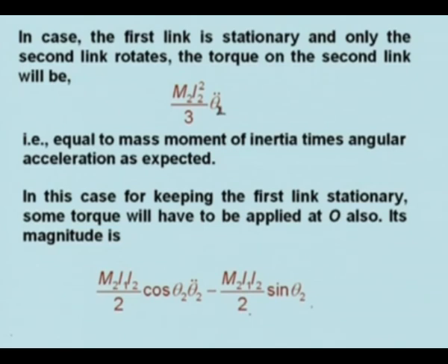So we see that this way, by applying only the basic principles of dynamics, we can solve these types of problems. Although a lot of expressions have been developed, if we apply only Newton's law to a particle, and remember the fact that these laws are valid in an inertial reference system only, then we can develop the equations for any type of problem.